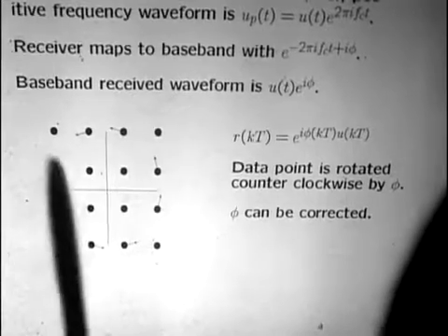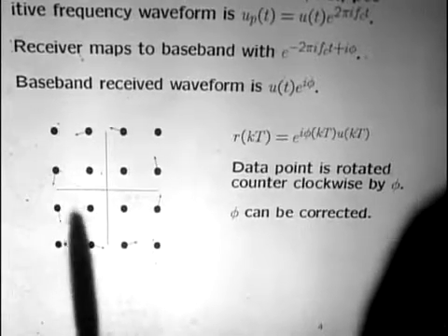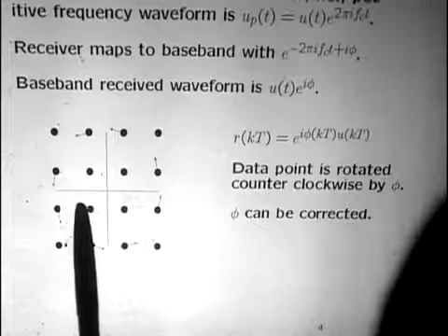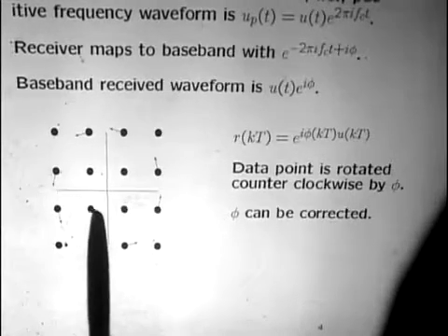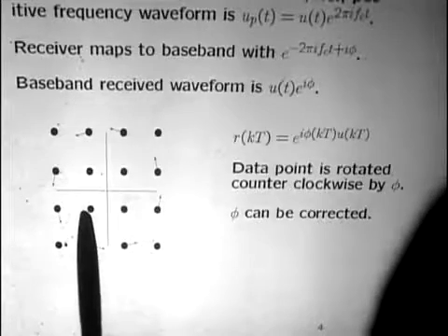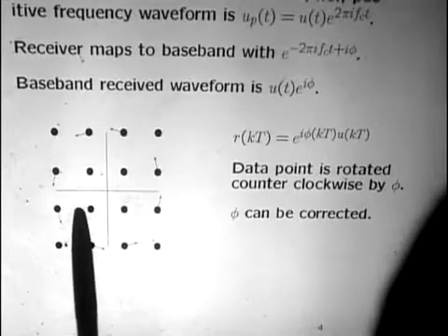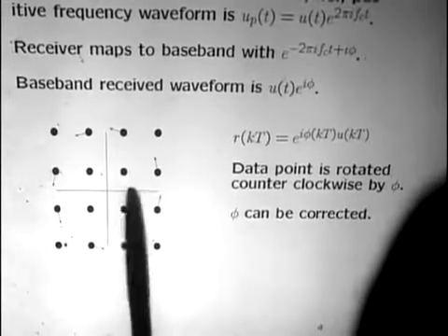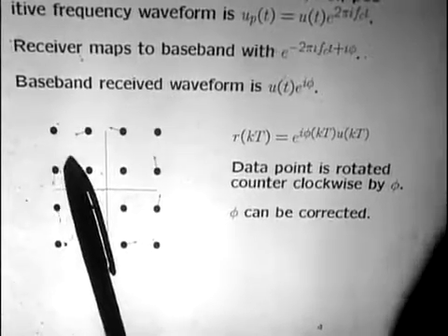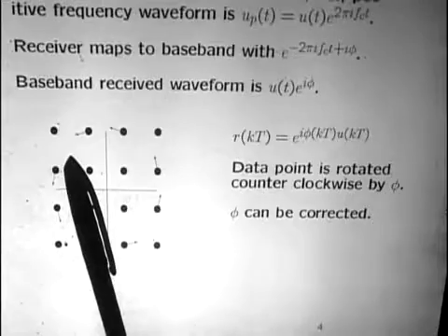How much trouble does that cause in trying to actually receive the data? Hardly any, because if the phase changes are slow enough and you average over a long enough interval, the actual phase errors are going to be extraordinarily small. So it's the noise errors that look big and the phase errors that look very small.